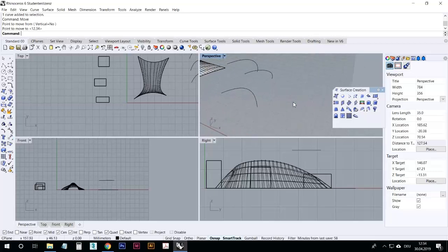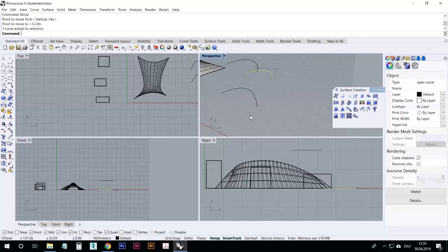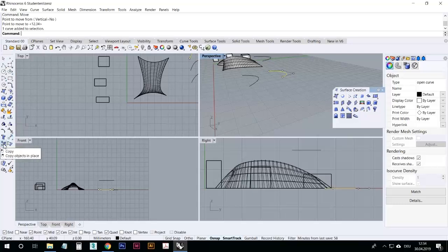So it was somewhere, the start point, I can show it again with the next curve. I go to move, either here, directly click, or you type it up here. So you see in the command line we have geometry, but we also have move, copy and rotation and scale, and analyze and flip direction. We have rectangular arrays.